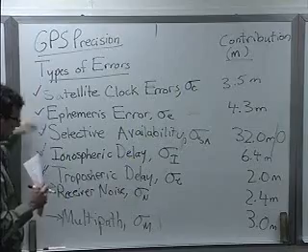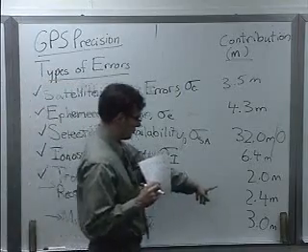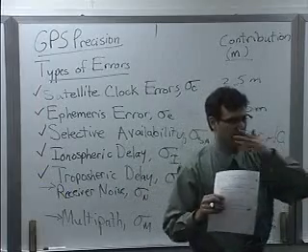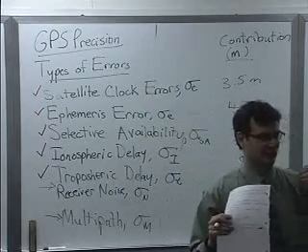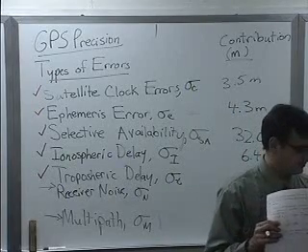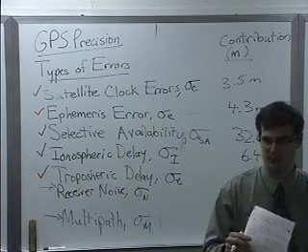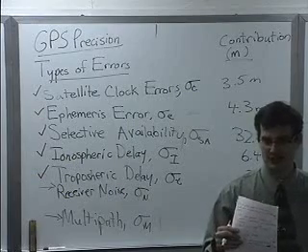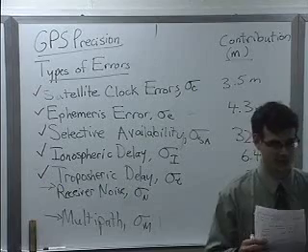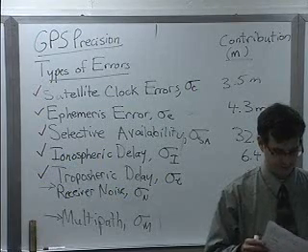In the absence of these other errors, that's when your receiver accuracy gets down to like 3 meters or less. And then to get down to the 40 centimeters, which is what Grant's talking about, that's when you need some supplemental technique. So you're using GPS and something else locally to do some correction factors. We'll talk about that in a bit too.